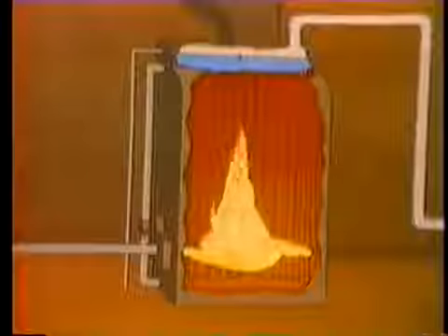In a coal-fired plant, a bright yellowish-orange flame in the furnace is a positive indication that combustion is taking place properly. Anything that jeopardizes the combustion process jeopardizes the flame and also jeopardizes the safety of the people in the plant and the plant's ability to produce electricity. If the boiler flame goes out, you have only seconds to respond.